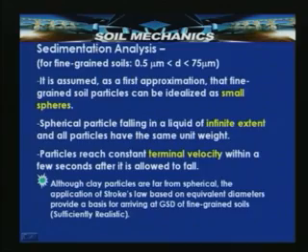Having seen the sieve analysis for particles coarser than 75 micron, let us look into the procedure for fine grained particle analysis, that is, particles passing 75 micron. We said that this analysis is required to be carried out if the percentage of fines is more than 12%.